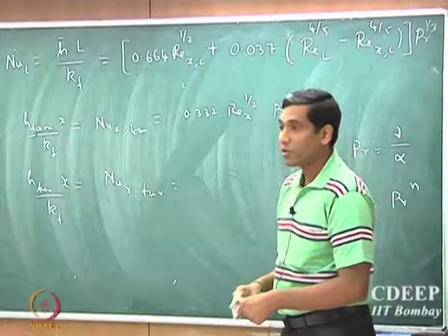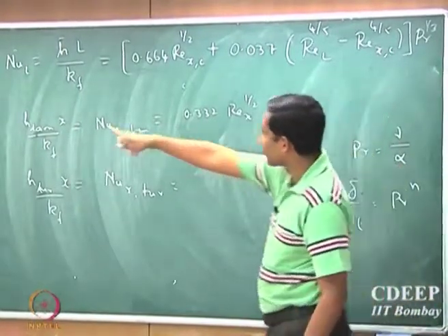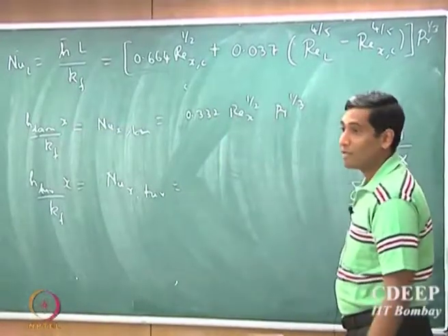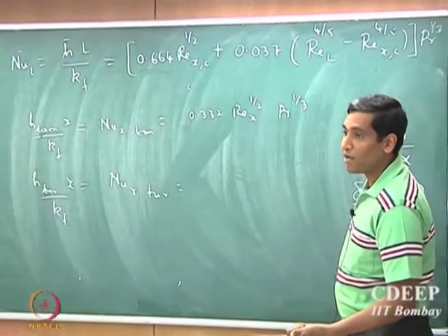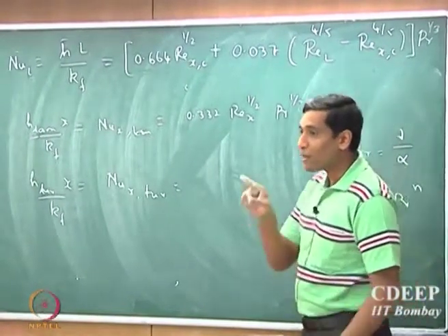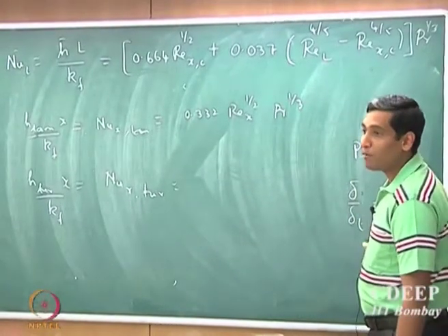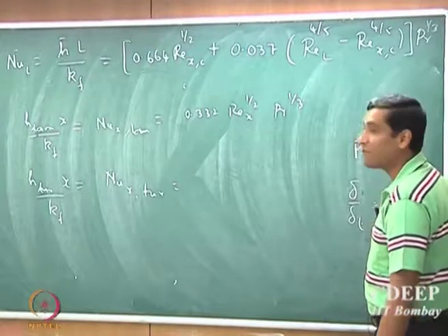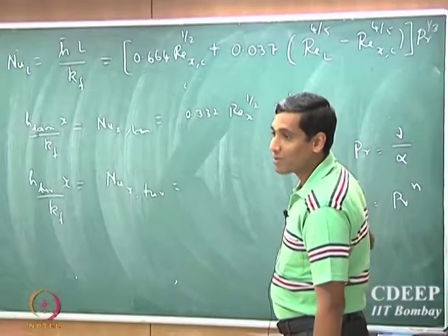Yeah, that's true. So it turns out for flat plate case it's the same. So note that it's not just the hydrodynamic boundary layer which changes. This is the ratio. Be careful, it's a ratio. It's both the hydrodynamic and the thermal boundary layer actually that is changing. Now when it comes to Prandtl number less than 0.6, the variations that you get in turbulent flow are very different. So you have to be careful how it is defined. This problem comes only when Prandtl number is less than 0.6.